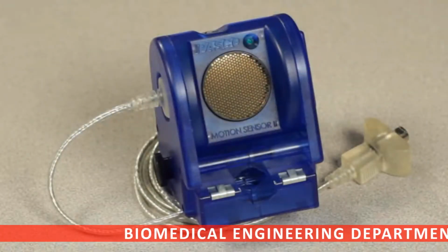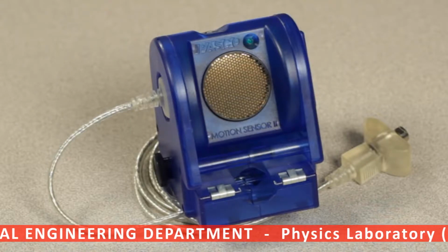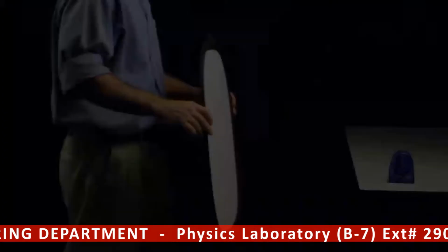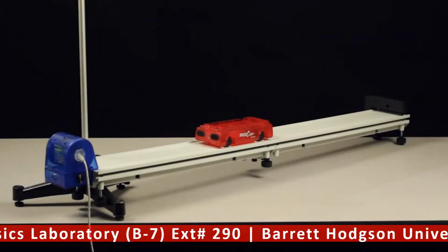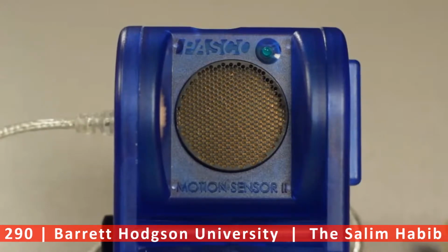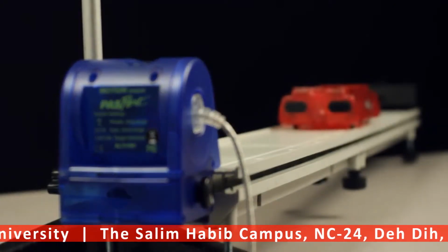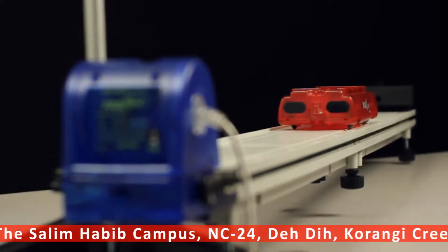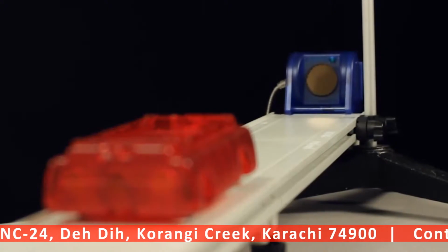The Pasco PS2103A motion sensor is used to measure and record the position, velocity, and acceleration of large and small objects moving in one dimension toward or away from it. The motion sensor makes measurements using ultrasonic pulses emitted from the gold transducer on the front of the sensor. These pulses travel out in one dimension from the front of the sensor until they hit a target object, at which the pulses are reflected back to the sensor.